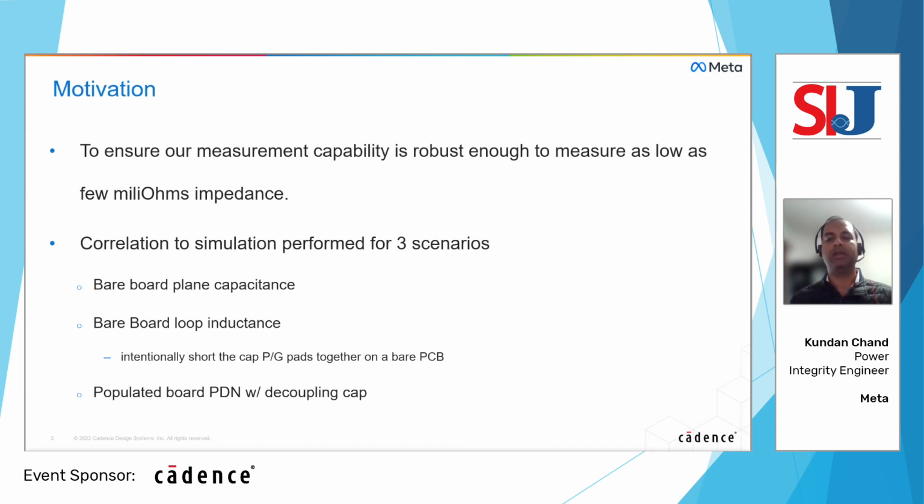So in terms of the correlation to the simulation, I can divide it into three categories, and that's how we started off with a bare board and did measurements on the bare board, without anything soldered onto the board, and just correlate the power delivery network plane capacitance. You have the power plane, and you're just correlating the capacitance with your simulation tool.